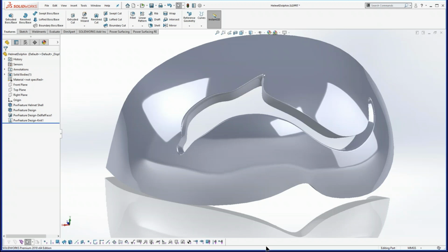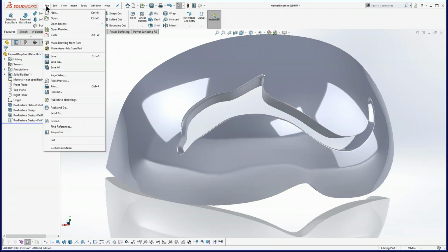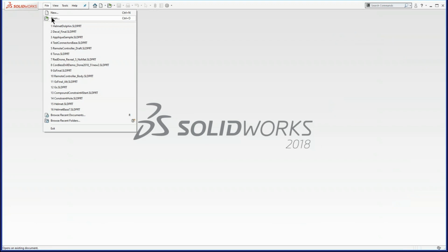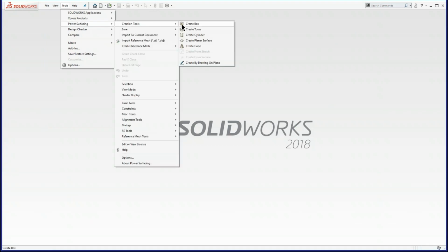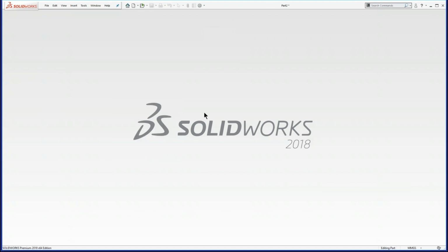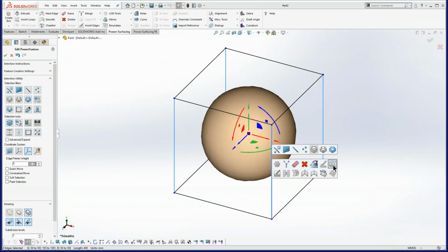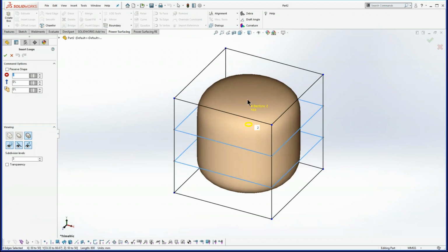Okay, Chris also was asking about doing models like the Lamborghini Aventador type of shape, which basically has a bunch of creased edges or harder edges, and we can do those as well. If you remember the electric car model we showed at the beginning when we were showing the customer images, that's a similar type of thing where it has a bunch of creased edges along with the smooth surfaces. So you can put in creased edges to get hard edges, but you can also make soft crease edges that are not fully 100%, that look sort of like a fillet too. So you can create all those different types of shapes and combine them and do all sorts of stuff with that.